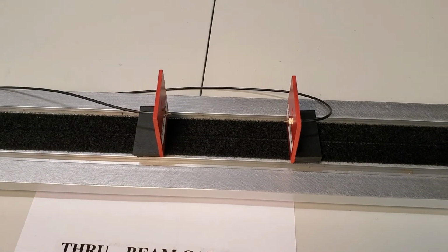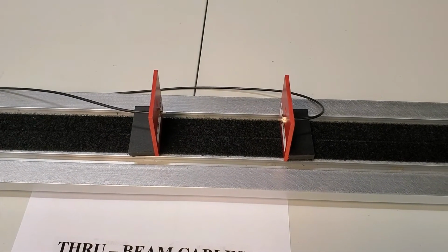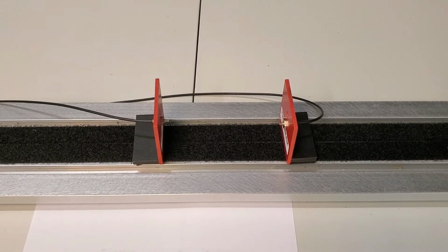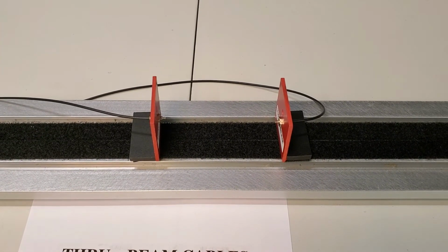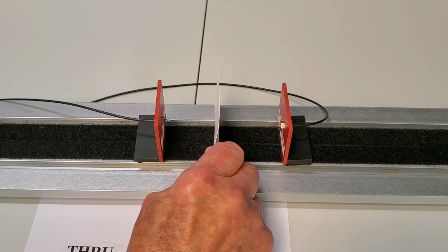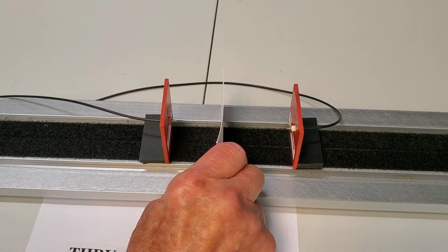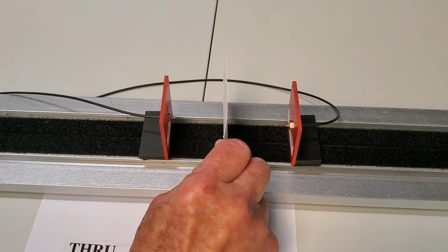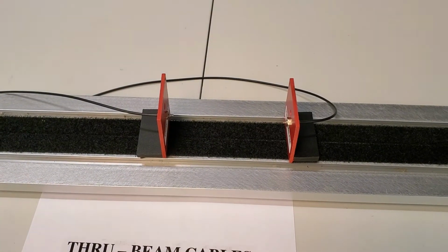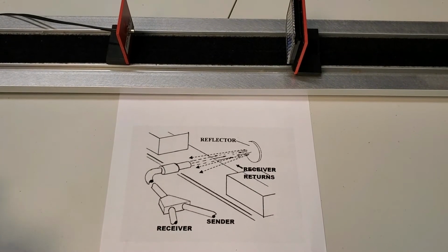Now, this can be done two different ways. This way, we're showing that when it sees the object, it will activate. However, we can change the mode of the operation so that when something is present, it actually stays off. So if somebody were to remove this, you would get a signal. This would be typical of a security system where you're guarding something or you don't want something removed, but if it does, it activates. The third mode of fiber optics classification would be called retroreflective.